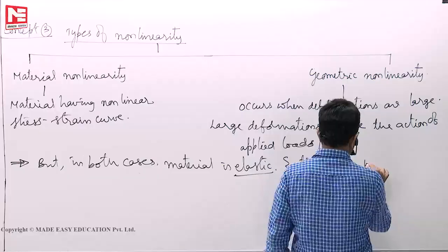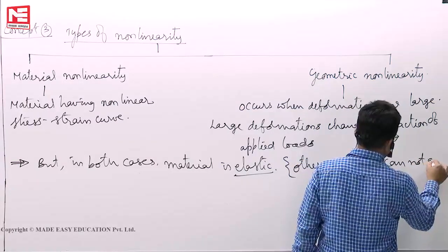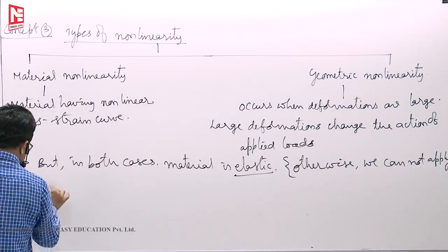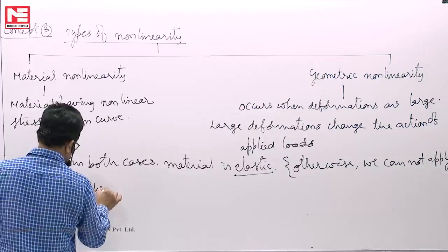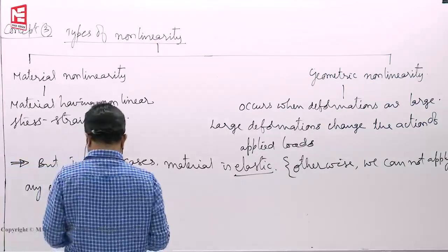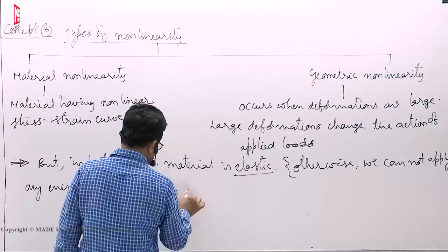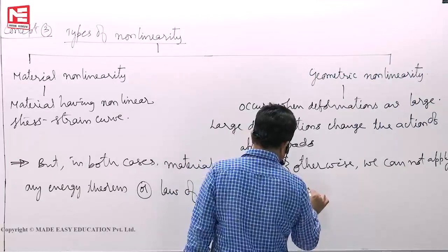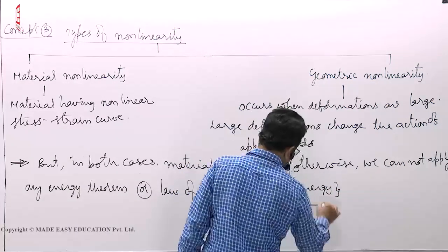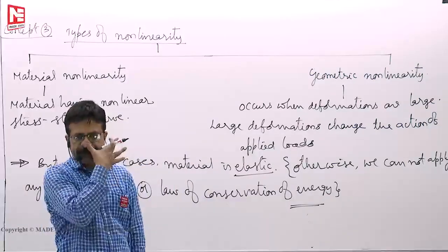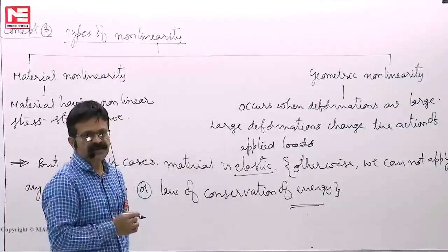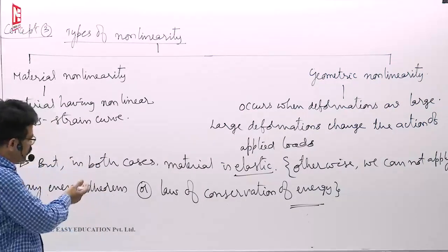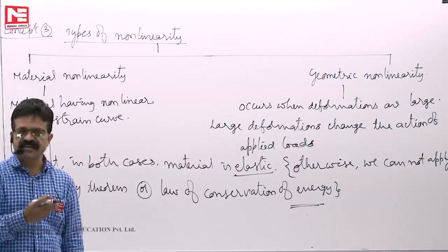Otherwise, we cannot apply any energy theorem or law of conservation of energy. That's the reason why whatever energy theorems that we study, they are applicable to elastic materials only. That elastic material can be linear or non-linear elastic, because that law of conservation of energy will not worry whether material is elastic or inelastic.